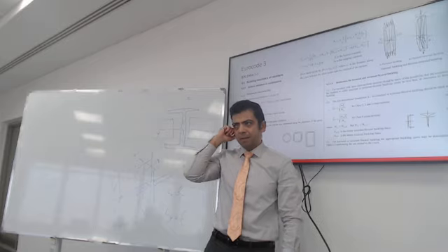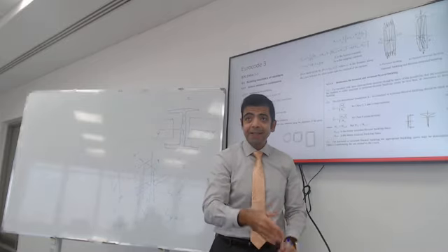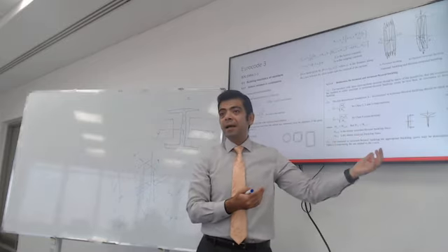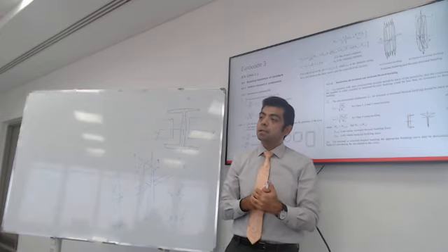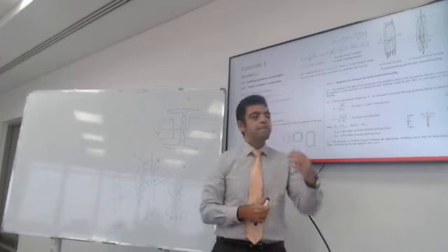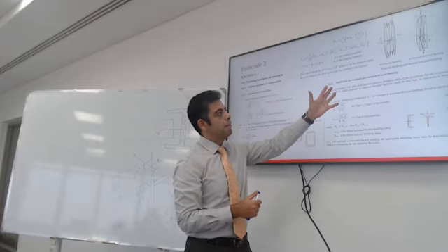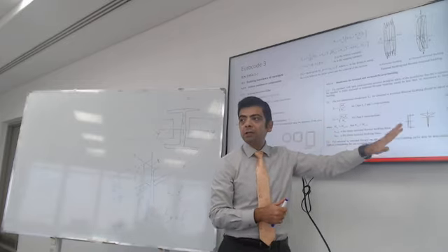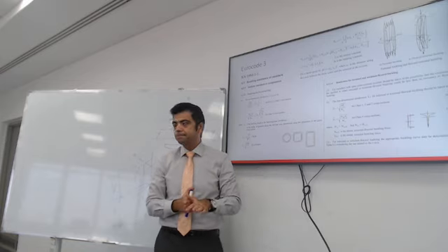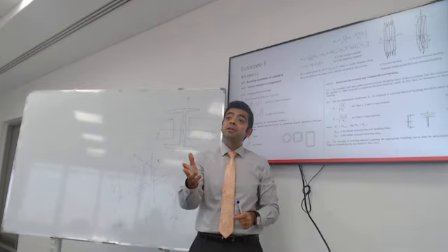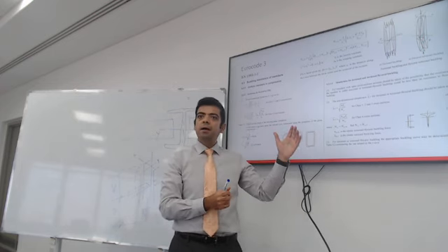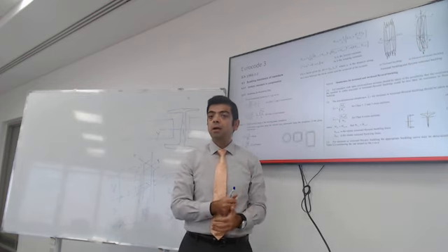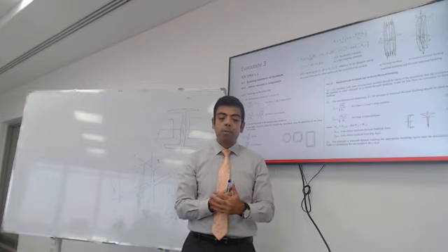It complicates things. So the code, luckily, gave us a way to design it. Think if we needed to figure this out on our own. That would be very challenging. So it's a good thing that the code gives us methods to design different types of sections. Having said that, you're the designer. If you choose an I section, just use the equations for flexural buckling.